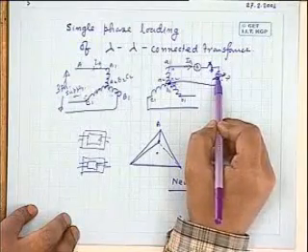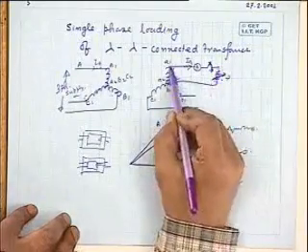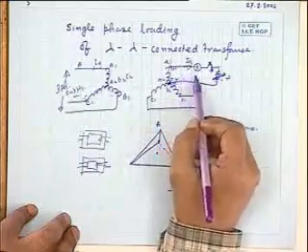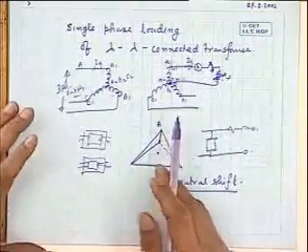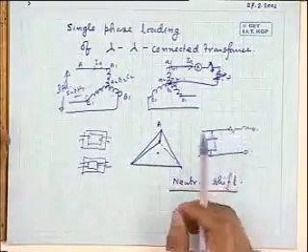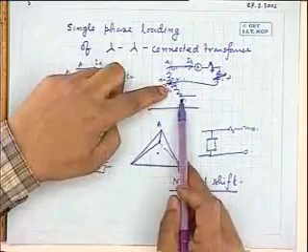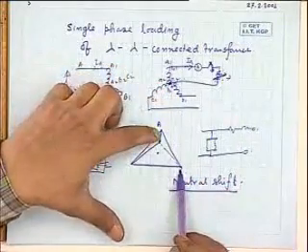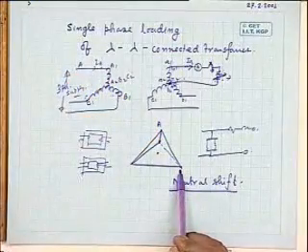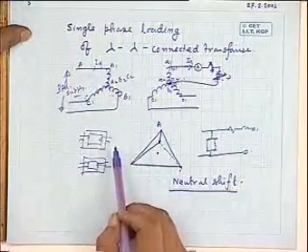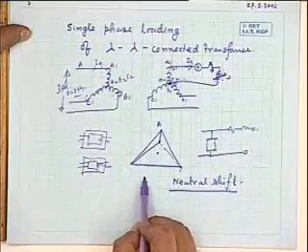And one can go to the extent of loading to a very high degree, means going to the extent of short circuiting. Of course, in short circuiting, what will this voltage be? 0. So this voltage goes on reducing. But should this be allowed? Suppose some current is not flowing, but should I allow this thing to happen? What happens to the voltage impressed across the other winding? That approaches the line-to-line voltage. So single phase loading sometimes becomes a problem, particularly with transformers having different magnetic circuits.